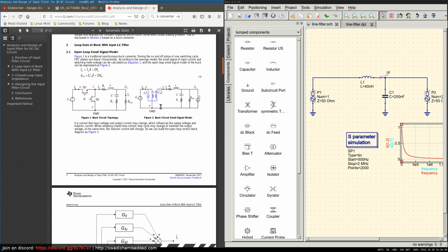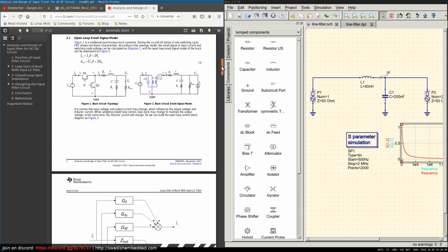But slowing down the edge of the signal will remove the high frequency harmonics that would otherwise come out of the device. And obviously, all of the serial lines should have ferrite beads on them. Ferrite beads filter the current slope in the signal line, which lowers the interference, because it is the current that induces voltages in things placed close to the circuit.